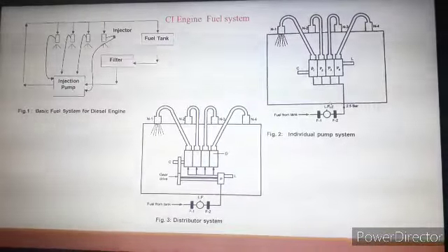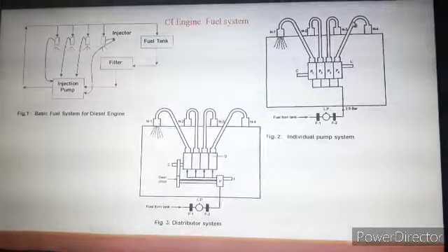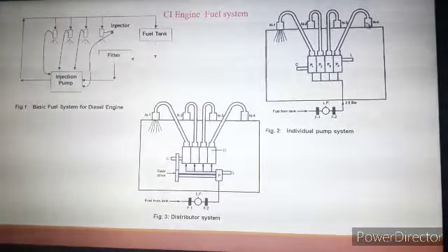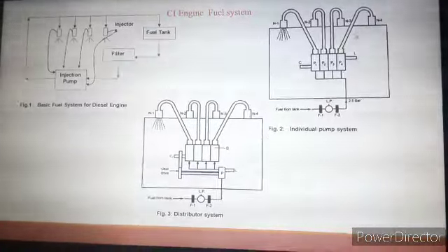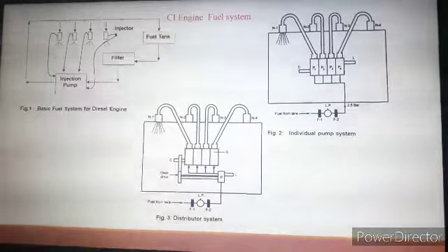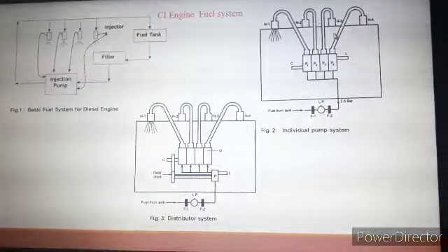So likewise fuel is sent from pump P2 to nozzle N2 and again to the next cylinder. Same thing is for nozzles N3 and N4. So here we have 4 different nozzles, and fuel is sent to the respective cylinder of the engine.